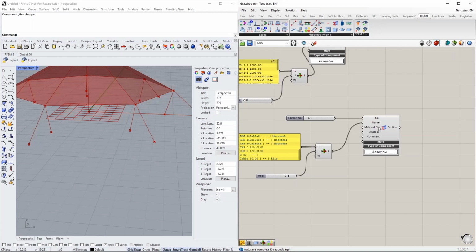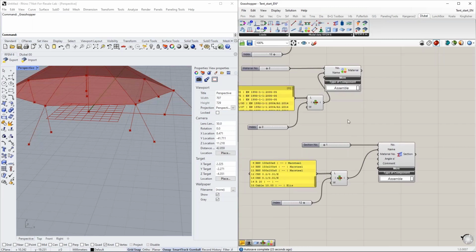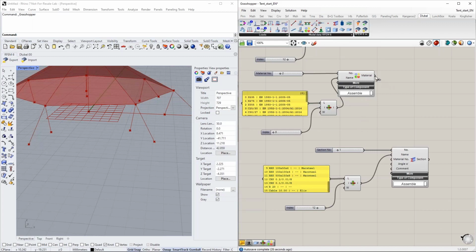the material number. I'm highlighting here the number because it's not intended to write down the name again in here. You have to assign the index number of the material. And I can do it quite easily. I can simply connect the material component with my S235 to this cross-section component. So this S235 will be linked to this cross-section, but it's only working because I assigned the index number beforehand. Yeah, this line basically transfers only the index number. This is what the component requires. So if you do not assign index numbers, you cannot follow this logic.